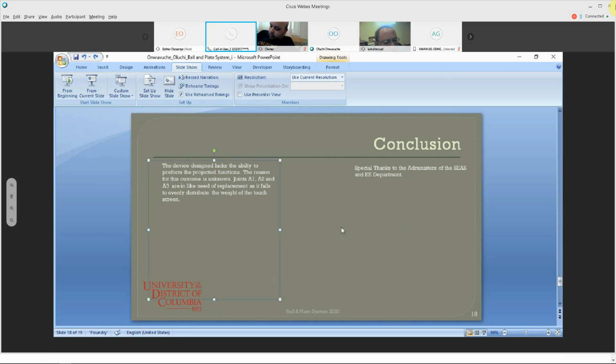So they're using 2, and then they try and support that with a centerpiece. Now, in my case, I tried to use 3 servo motors which support the platform, and also it's supposed to take in information from the Arduino based off the X and the Y measurements it receives from the touchscreen.